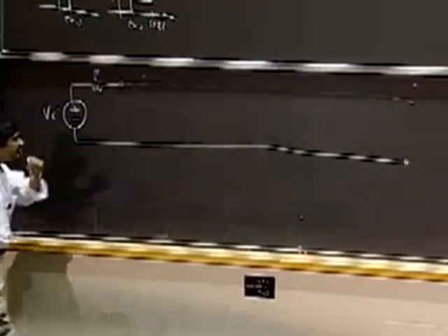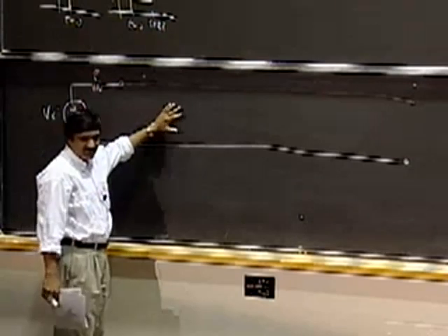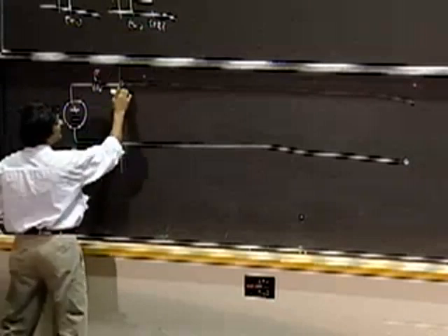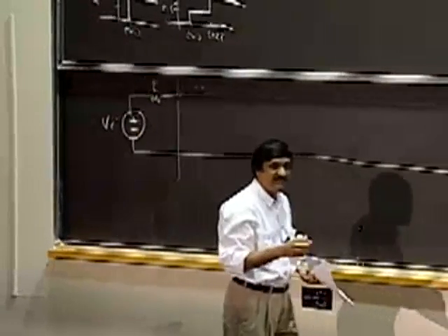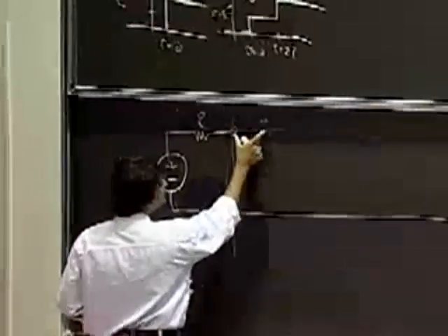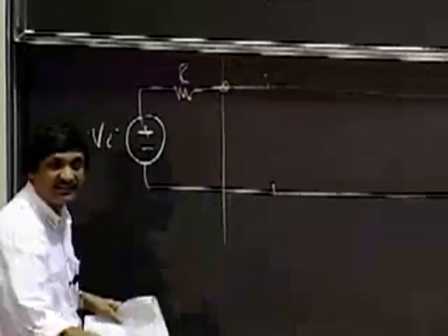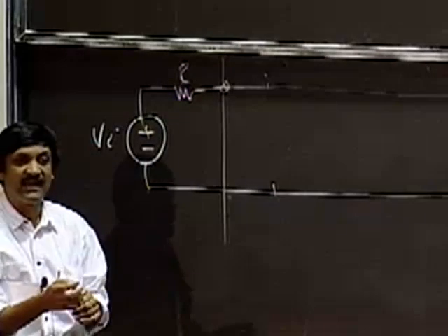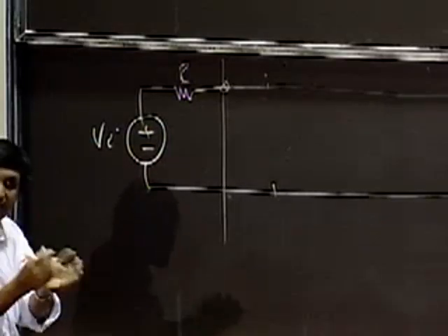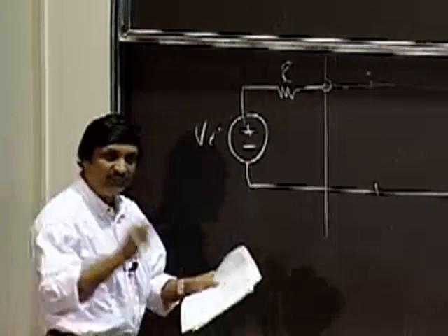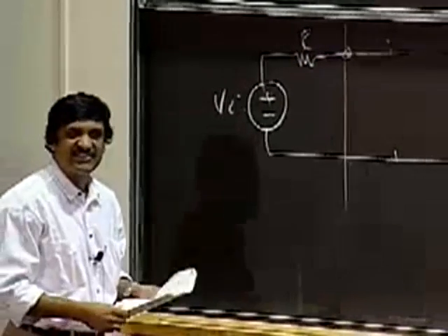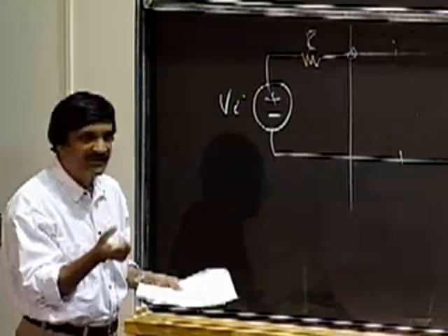So although this is a wire, to understand the mechanics of what's going on, I really have to model it much more accurately. The way to model a wire like this is that every small element of a wire has associated with it some inductance. Let's take a small segment of the coax cable here. The coax cable is a small core surrounded by a metallic shield. That's a ground. And when you have a wire surrounded by a metallic shield, that also has a capacitance. Inductance and capacitance.